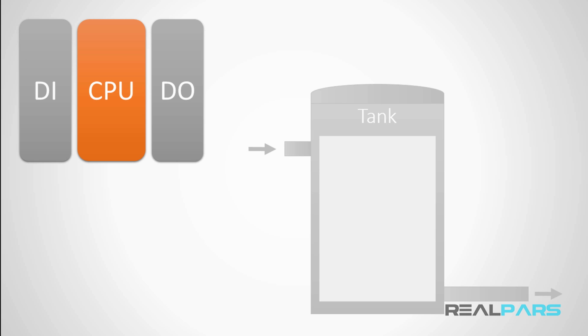In order to see when the tank fills up, we place a 24-volt DC float switch in here, and we can also use a 24-volt solenoid valve in order to connect and disconnect the outgoing water flow from the tank. This float switch has a simple contact, which is open by default, and when the liquid level in the tank gets to a certain surface level, this contact closes up.